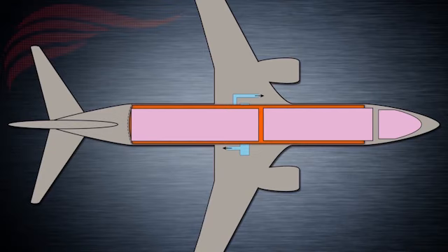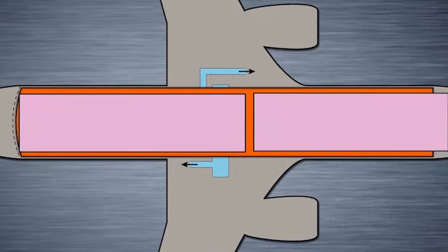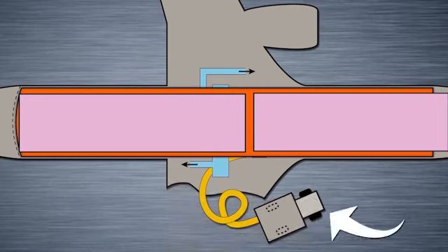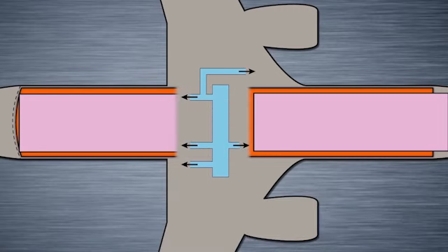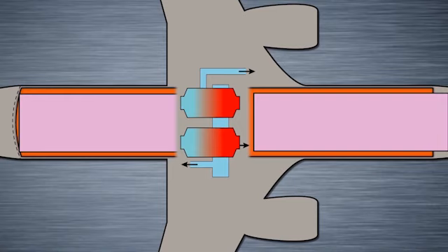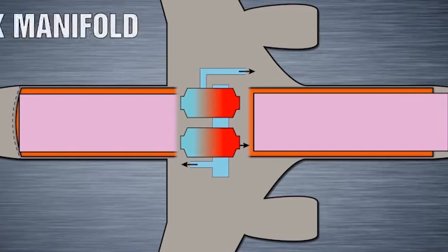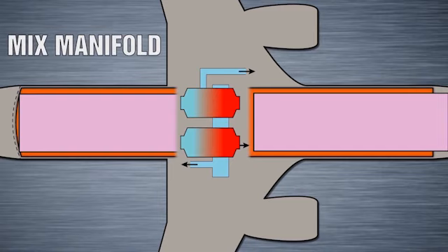For air conditioning purposes, the 737 NG cabin is divided into 3 zones: the flight compartment and flight deck, forward passenger compartment, and aft passenger compartment. Conditioned air may come from either of the following sources: ground-supplied preconditioned air, recirculation system, and air conditioning packs. All sources supply their conditioned air to a main distribution manifold, also known as the mixed manifold. This essentially acts as a giant pool that collects conditioned air from all sources and supplies it to the respective cabin sections that require air conditioning.